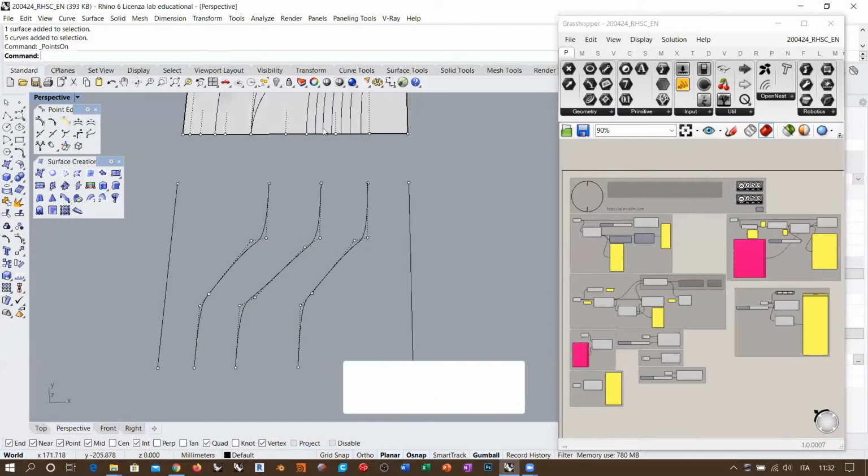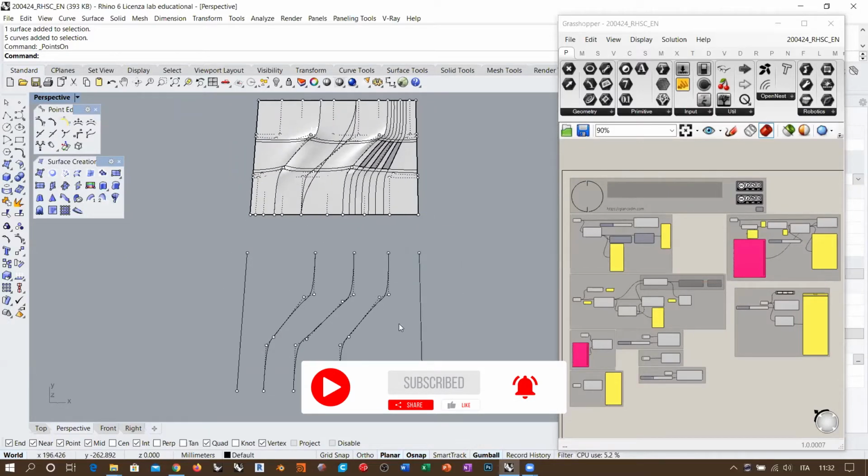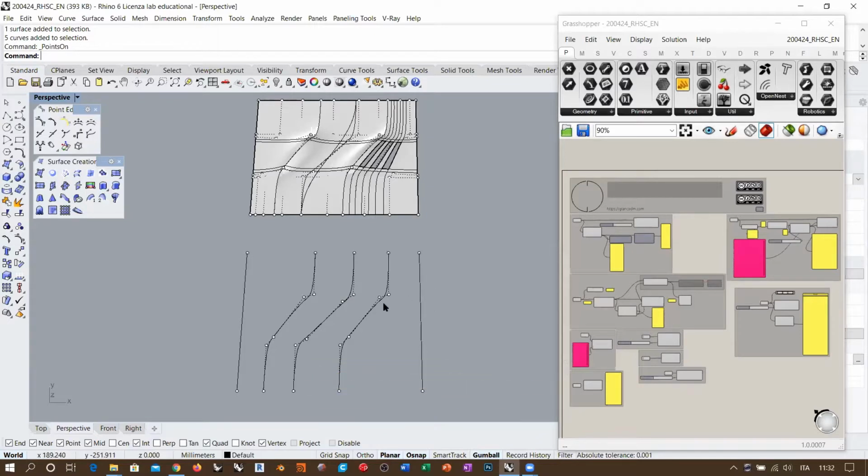Okay, so if we try to repeat this construction here, this building for this surface, using exactly the cross section, we will run into some problems. The topology of these inner curves here is identical because they come from the same surface that we obtained with the first execution of the loft. So all three curves have 6 control points and degree 3.